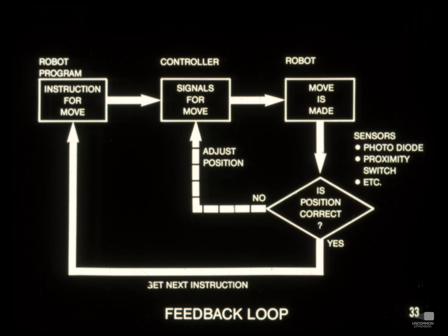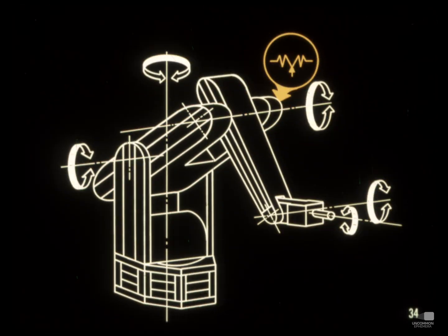Various feedback devices have been used to supply the robot's controller with the necessary positioning information. With such feedback data, the computer and/or controller can make calculations and, consequently, send very accurate positioning information to the robot arm. The simplest of feedback devices consists of varying an electrical parameter as a function of the position of a robot axis. For example, the moving joint can position the contact arm of a rheostat, the magnetic slug of a coil, or the dielectric of a capacitor, thereby producing an electrical parameter change which can easily be detected by